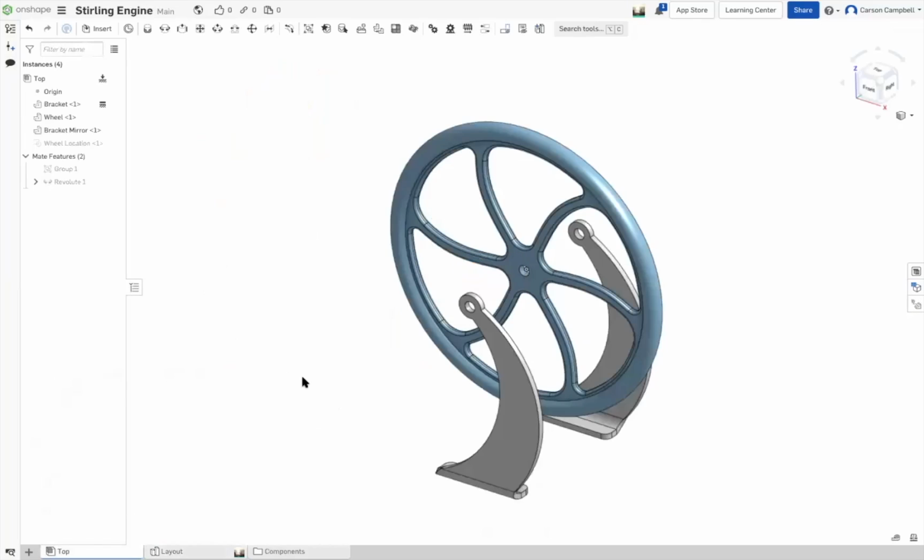In most designs, eventually you'll want to be designing an assembly. A lot of people will design everything in just a part studio, which is a great way to get started, but I don't think you can handle all the scenarios that you need to get everything done. So we're just pushing everything into the top level part studio just to show you the relationship between a top level assembly and a part studio. A part studio generates geometry and the assembly designs the part. And we're just going through the steps to do that.